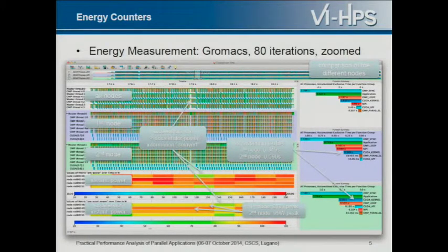Another thing that we see here, which is also an artifact of how it's measured, is that the accelerator, for example, is idle at this point in the program flow. There are no CUDA kernels running here, but this energy measurement for that is actually delayed. So first, the instant power seems to be updated by the CRAY system, and since this is 10 Hz here, you get it like one cycle after that, and the accelerator instant power seems to be updated even one update cycle later. So you always have to be a little bit careful of how precise the measurement you have done actually is.